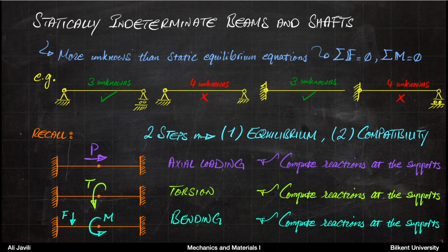On top of that, if you calculate the elastic curve, you can also impose the boundary conditions from the problem, so they give you additional conditions. And usually, this is how you would need to solve the problems. So you write your equilibrium equations, and then if they are not enough, you write your elastic curve, and then you use the compatibility of the elastic curve to proceed. Now you use that compatibility maybe internally, so for instance, it could be the right portion and left portion of the beam, or it could be just compatibility with the boundary conditions. We will learn that in a few examples together just now.